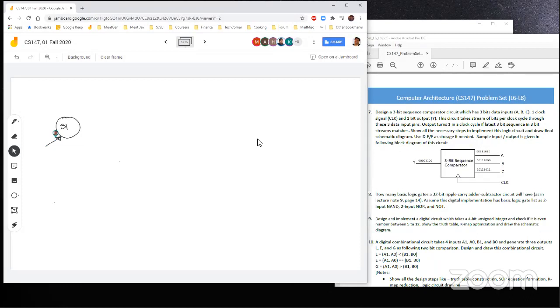And then we can say we are operating on this variable M, right? If M is 0, not matched. M equals 1, that means matched. So if M is 0, I will go to the same state with output 0. But if it is 1, I go to the next state saying that I got 1 match, okay?